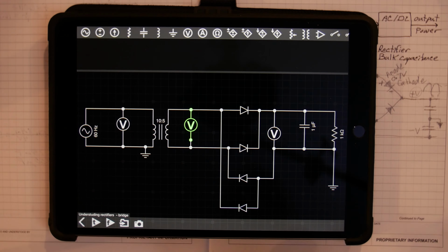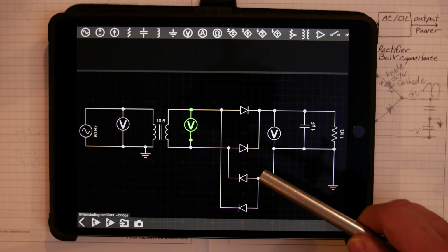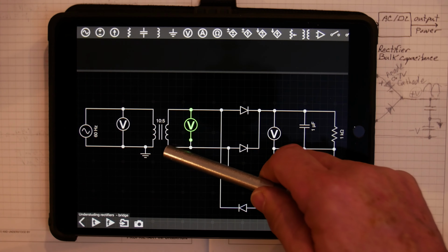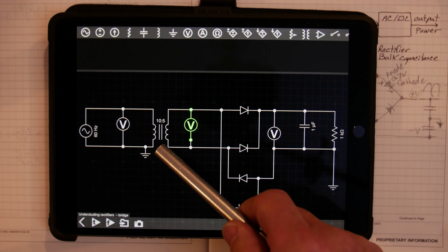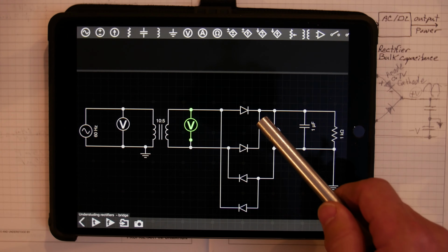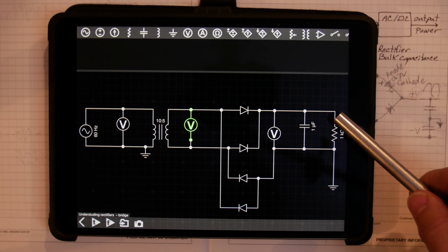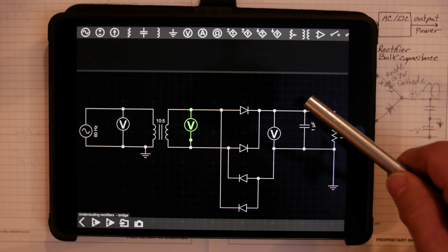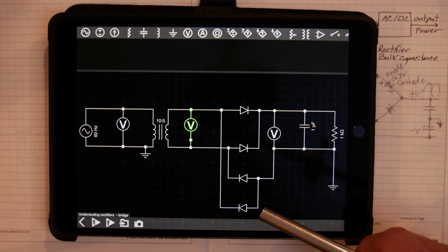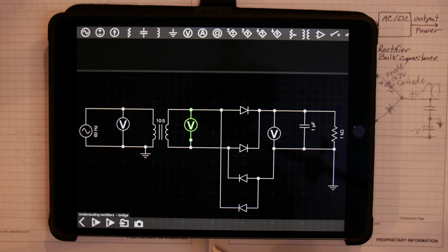Okay, we're going to turn this on so you can see it. I just want to give you a heads up what to look for. That's going to happen during one side of the cycle, right? When the cycle flips around where this becomes plus and this becomes minus, then the current goes this way and comes up here through our load. So it's always going through our load the same direction because we want DC up here. It's always going to be plus up here. Comes down, comes around, and then comes to this diode and through our transformer. So that's got kind of a strange path.